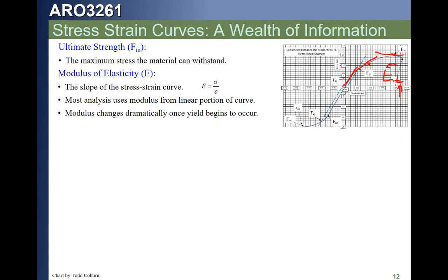We're not going to use that, but we should be aware that the modulus is actually a function of the stress. Usually we're going to use the modulus of elasticity from the elastic portion of the curve. That initial modulus is what we're going to use for most everything we do, but we need to understand that that's not strictly correct. That's an approximation, okay? Our ultimate strain is just you take the furthest most point shown on the stress strain curve and we read what the corresponding strain is.